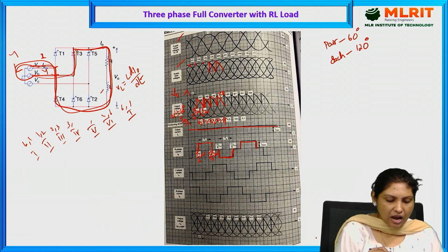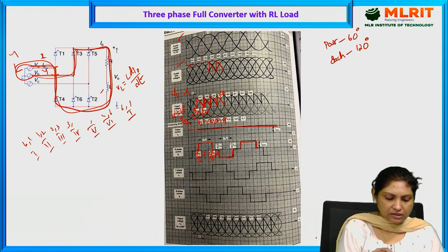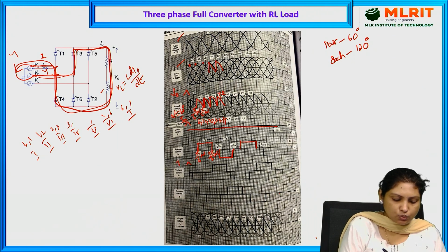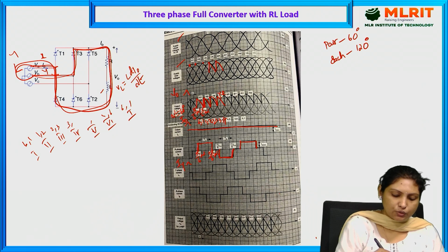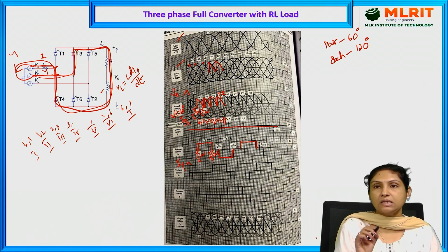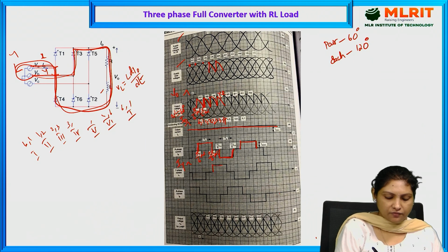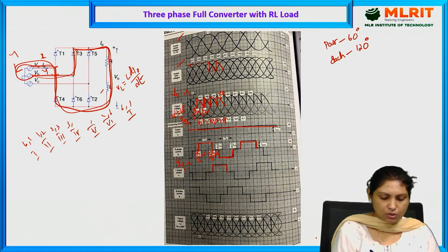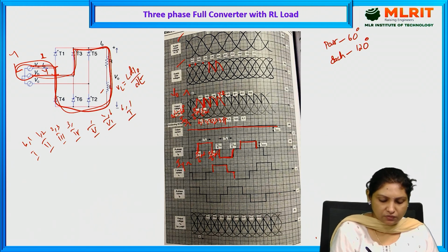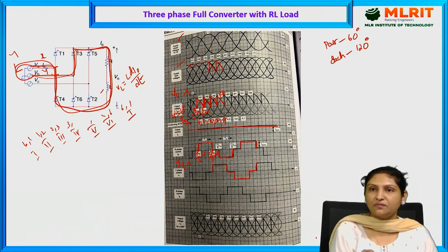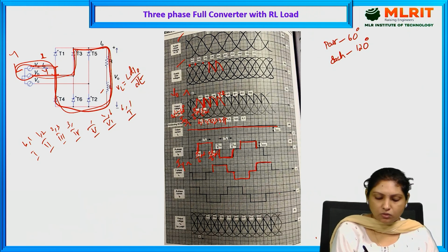And then IY phase. IY phase in the sense current through the Y phase. Current through the Y phase will be appearing when Y phase appears across the load. So during which Y phase appears across the load, and again it is off, and again see BY phase and RY phase, during which Y phase current will be negative, and again 0, and again when Y phase is conducting, we will get the positive current.